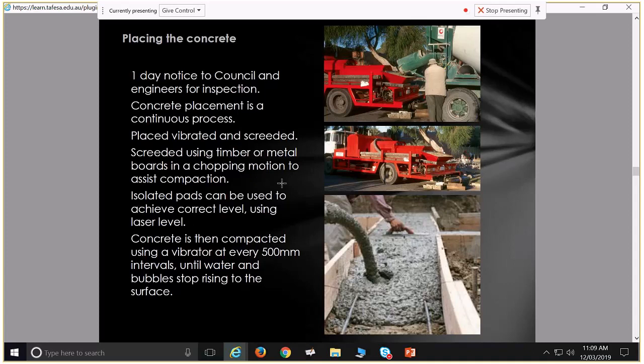And if I'm forming up a lift shaft like that, I'm not going to be using low slump concrete. That's going to be high slump concrete because I'm pouring it down a long distance. I want it to settle in there. And when we pull away that formwork, we don't want to have air pockets and everything exposed. We have to have very high slump concrete.